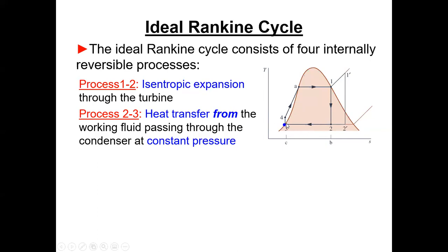We're showing that just to the dome, which means it's all saturated liquid. Probably in reality, we're going to go over into compressed liquid a little bit to make sure that we don't put any vapor into that pump. Pumps don't like vapor, just like turbines don't like water droplets. Slugging that pump is not going to help it.